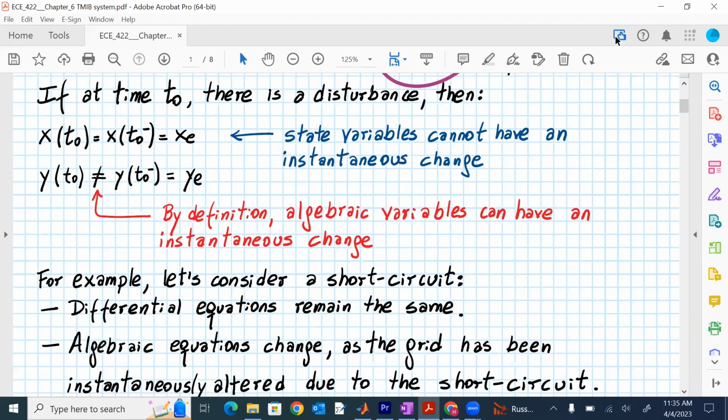What disturbance? We have considered short circuit in the past, and we will continue using short circuit for this system. Short circuit is a type of disturbance that does not create any power imbalance. That is very attractive for the model that we have, because we do not have a governor in a turbine model. If there is a power imbalance in the system, then the power generated from the generators needs to be adjusted. And that will not happen with the model that we have so far, as we have not described the governor in turbines yet. So we will stick with the short circuit for now.